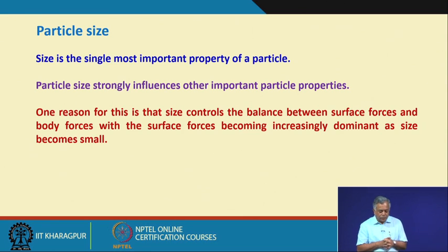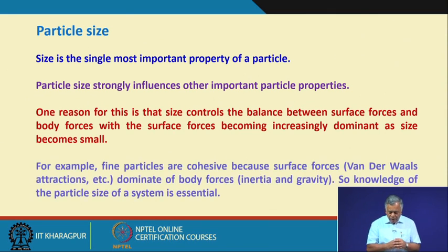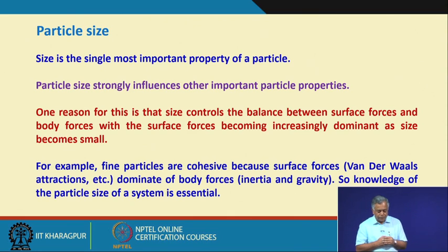When the particle size becomes smaller and smaller, the surface forces become the dominant forces. Examples of surface forces are van der Waals forces, and they are much more dominant than body forces like inertia or gravity. Suppose I have 10 micrometer particles, or all particles finer than 10 micrometers.